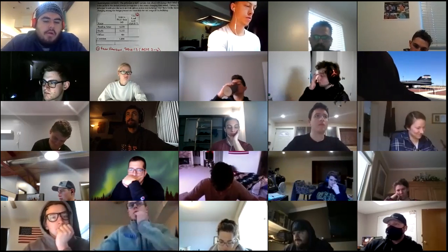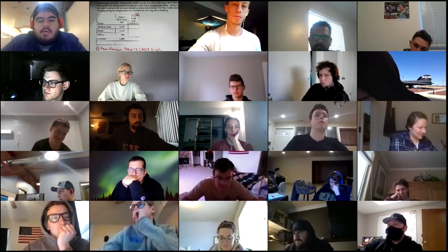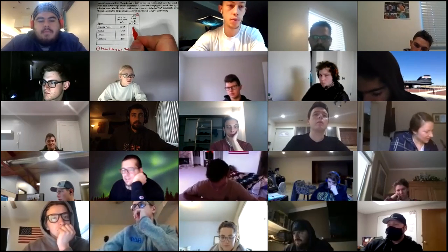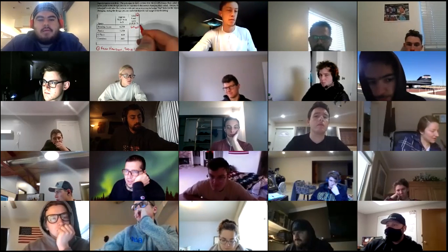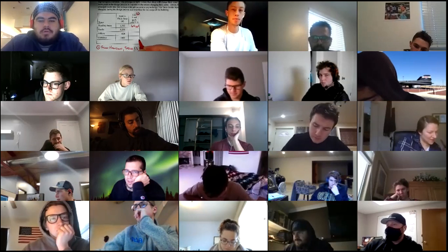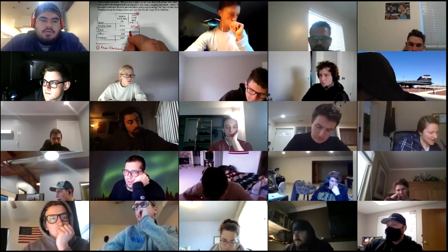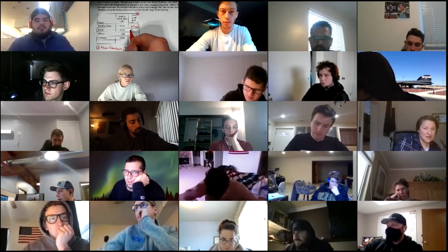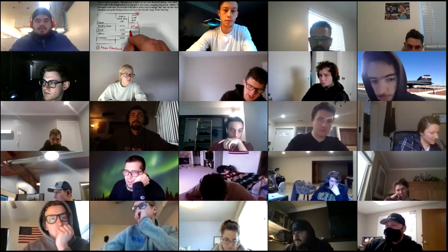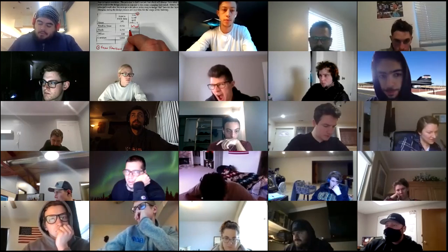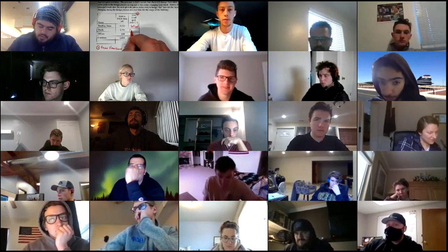What do you find for a reading area in a library for a live load? Anybody? 60 PSF. Absolutely. So got 60 PSF there. What do you find for stack areas? It's 150 PSF.